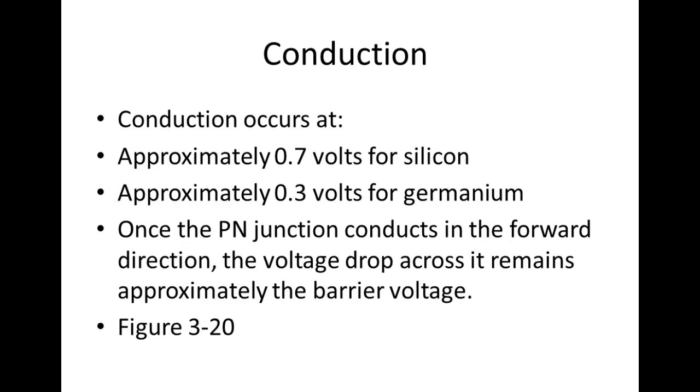The other VF they give you is going to be a typical VF. They'll call it VF average, and this is what it should average out to. But you've got to understand, as the current goes up, that is not a conductor, it's a semiconductor. It's been doped to be more conductive, but it still has some opposition. So as the current goes up, the 0.7 of a volt is going to go up, and if the current goes down, it's going to come down.